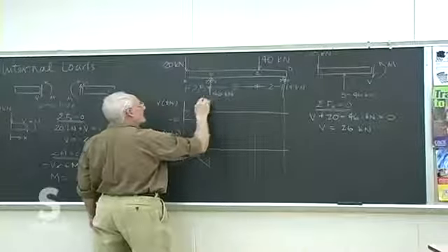Minus slope makes sense because we know we have to come to this roller support end, which will have no internal moment left in the beam. So we know we have to finish at 0. So the minus slope makes sense. And if we put the values in, we know that we start exactly where we left off at the moment.